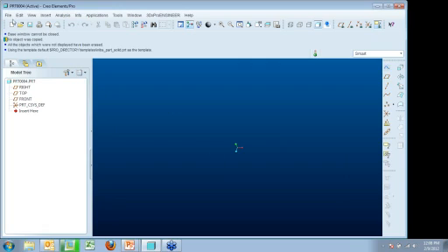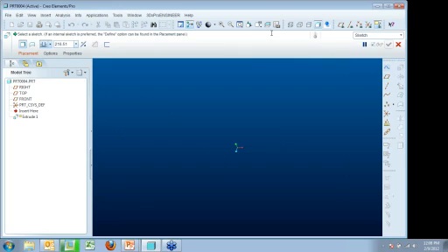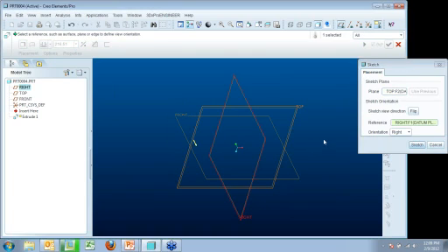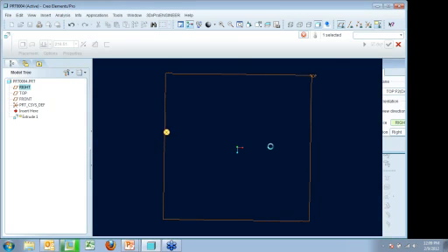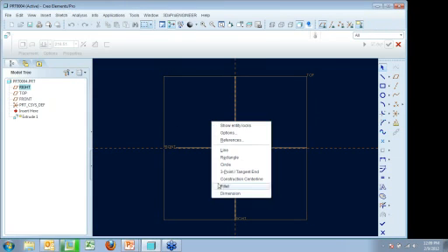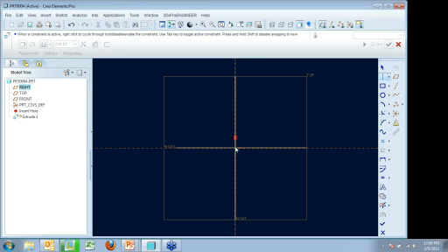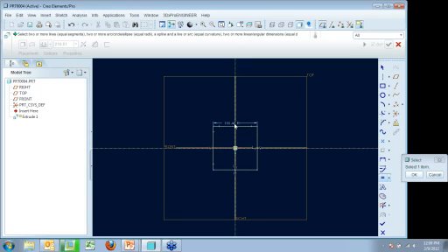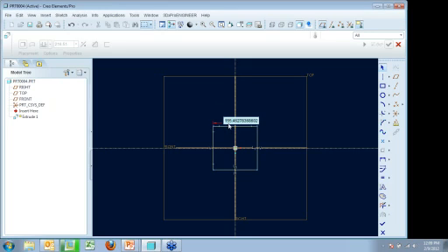So I'm going to show you. I'm going to sketch a real simple extrusion here, and you can see all of the different steps I'm going to take. It's going to be real simple, square, with another square on top of it. So I have to go in, create some construction center lines, make my square, then actually go in and set these two sides equal to each other. And we'll make this 250.